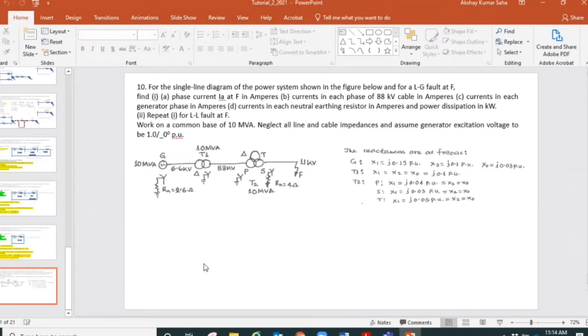So when we have to connect two transformers in parallel, we need to make sure that certain conditions are met, and especially if it becomes a three-phase transformer, the number of conditions becomes more. If we have a single phase transformer, we have to make sure that the frequency is the same. If one transformer is operating at 50 Hz, the other must operate at 50. If transformer one is operating at 60 Hz, the second transformer must also operate at 60 Hz. There are reasons, we can explain that one.